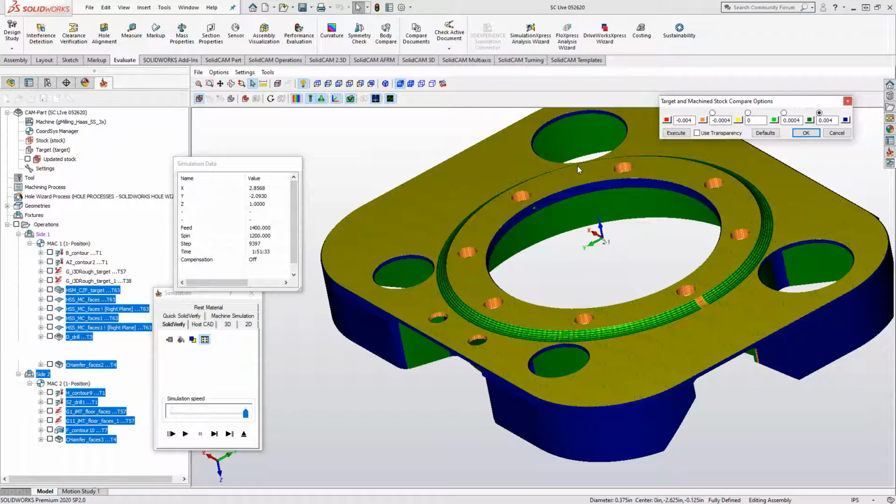We just did horizontal machining. So these walls were left alone because there actually is no wall floor for it to do. These are through holes. But the holes themselves, they have some coloring that indicates it's between 0 and 4/10, pretty much on size. And all these other surfaces have that yellow color indicating again as well that there's 0 amount of material there. The only thing that's left is, again, the outside wall, again, because we didn't do any walls.